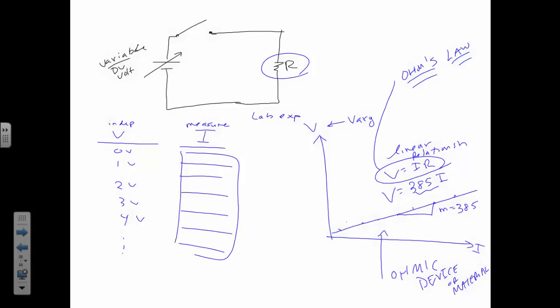When you heat something up, it changes the material properties a little bit. If you heat an object up, what do you think happens to the resistivity of the object? Goes up or goes down? Think of the atoms. What do the atoms do when you're heating something up? They're vibrating faster. Now you have to run through vibrating atoms instead of stationary atoms. What's going to happen? You're going to collide a lot more. Your resistance goes up. So resistance is, to an extent, heat dependent.